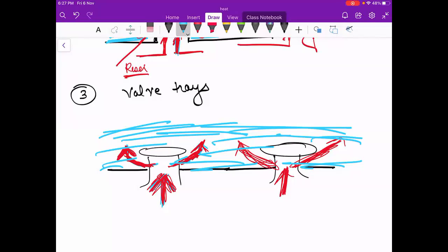It means that when there will be no vapors in the system, this cap is closed. As the vapor is increasing, it will lift more. Okay, so more vapor will come, more lift will be there, and more vapors will go outside. Yes, you can say it is just like a pressure cooker whistle, means enough pressure is built up, then it will release it. So basically that much amount of pressure you have to maintain in that system.